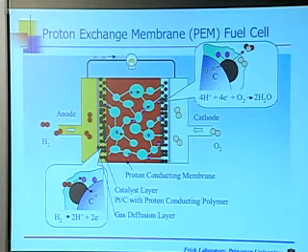And one of the big tricks in this whole PEM thing is that you need to keep water in the electrolyte because, in fact, the protons here are moving through water, you can see. So no water, no proton motion, high resistance, no fuel cell. On the other hand, it turns out that if you get water in the weaves of this cloth, it blocks the pores, and you can't get the gases through. So that's called flooding.